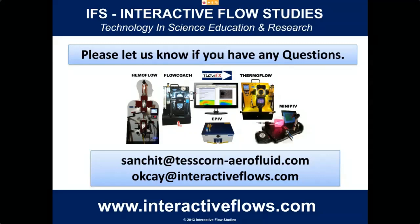Of course, we have another system that measures the shear flow. It's a system that you actually bolt onto a surface from under. So you drill a hole and you bolt it through. And so, that then solves a lot of the problems. So it has challenges, but measuring boundary layers is very challenging in itself. I'm not sure how close we can get to the boundary layer with the general systems that we have.